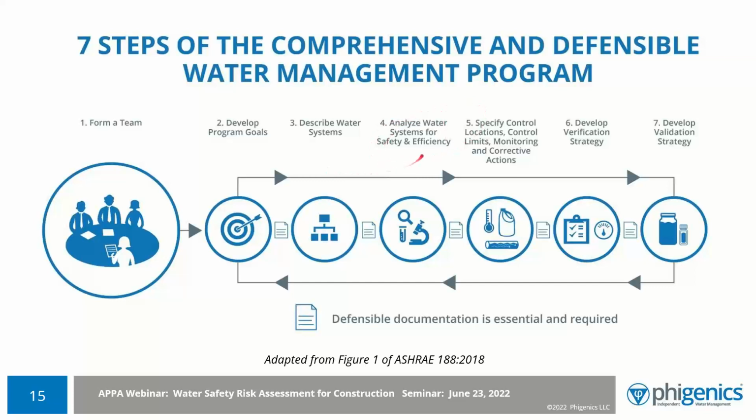You have to analyze the hazards of the building water distribution system, and you have to apply control: flushing, disinfection, etc. What are you going to do to control the hazards is step 5. Once you have the system in place, the program in place, you have to verify monthly, quarterly, biannually, annually, whatever your team decides or what's appropriate for the occupants. You have to verify that the program that you have written is in place and that you are checking that it is being implemented as designed.